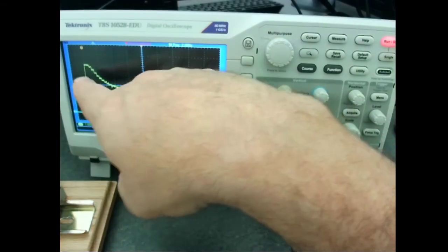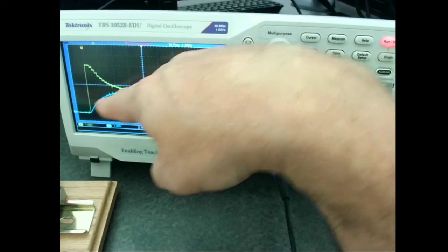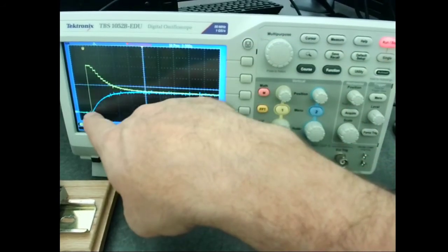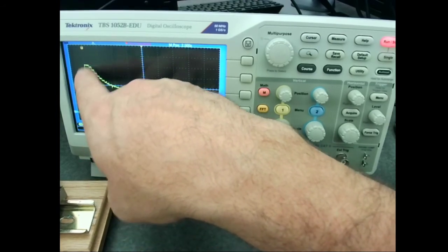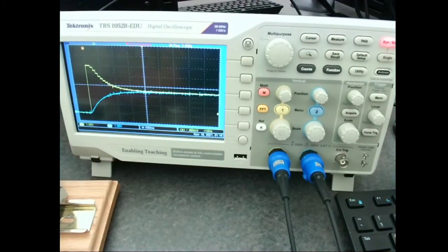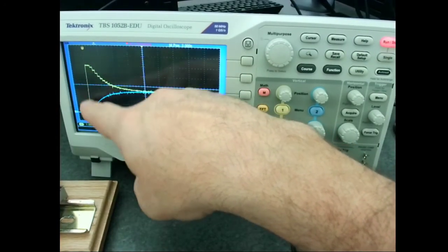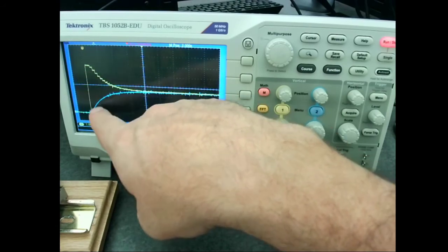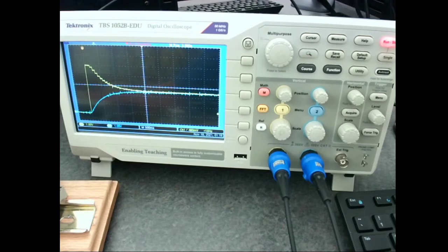All right. Now, what you're seeing here, this yellow is the control signal. The control signal is maxing out at 5 volts. 1, 2, 3, 4, 5 volts. Because that's the maximum error. Because my set point is 5 volts. And so the error is 5 volts and my gain is 1. So I'm multiplying it times 1. So I have a gain of 1.